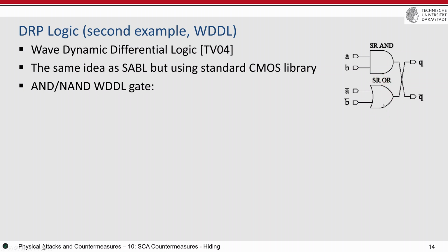You may think, okay, how does this work? You see here A and B are connected to the AND. And here the A bar and B bar are connected to an OR gate, and this is actually a NAND gate. It means that A and B give Q bar as the output, and if you invert the input, you actually invert the output, easily, and then you change the gate to the OR gate. This is clear. If you have A and B equals Q bar, and I want to have Q, then it will be A bar or B bar. And this is exactly what you see here: A bar and B bar, OR, and they make the Q.